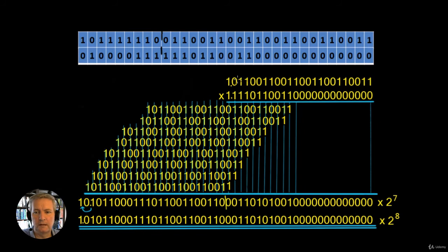So we append that 24th bit. We've added on the value of 1 and a value of 1 here. So now what we're actually multiplying together are two 24-bit numbers, the 23 bits plus the 1 and the 23 bits plus the 1. Whenever you multiply together two 24-bit numbers, you're going to get a 48-bit number.